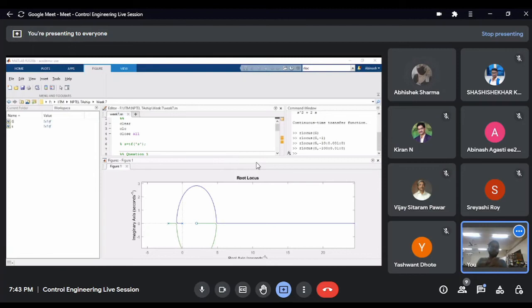Yes. So for root locus, what we do is every point in the complex plane that satisfies the characteristic equation being 0, that is part of the root locus, correct? Yes. So for that we equate kgh equal to -1. That is kgh equal to 1 at 180 degree.